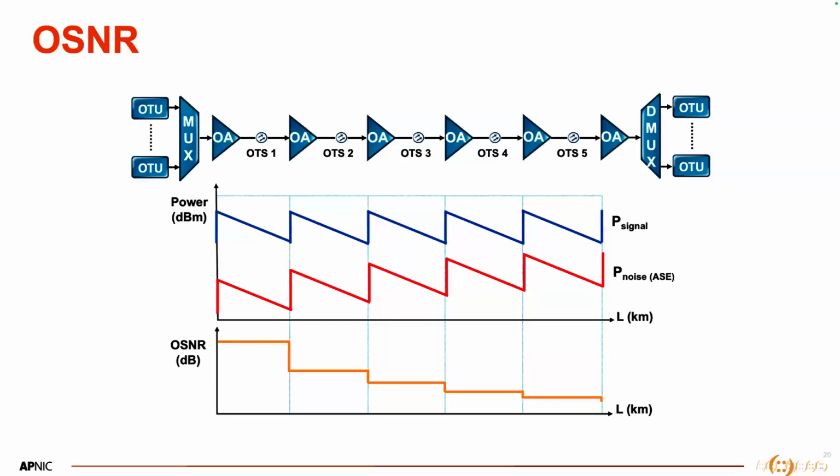But if the OSNR is low, that means though the wavelengths have very good optical power at the destination, the data they are carrying will be error-prone. They will face degraded quality of data or degraded quality of service at the destination only because of this OSNR. So are we clear between these two? One concept is optical power, another concept is OSNR.